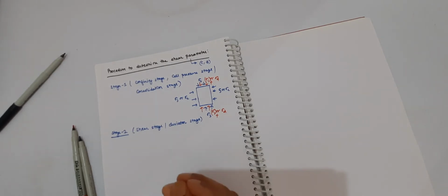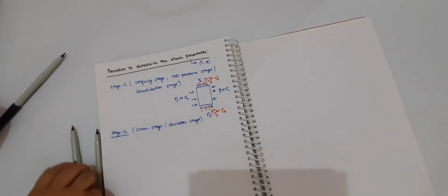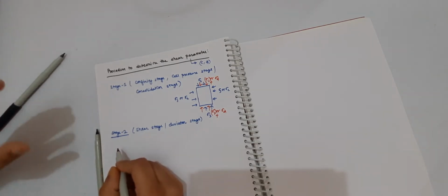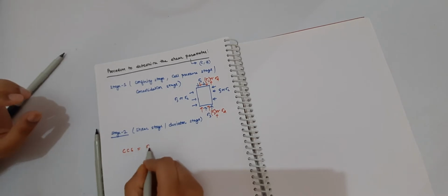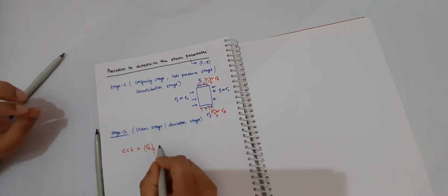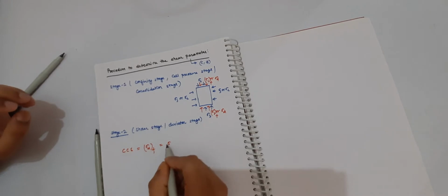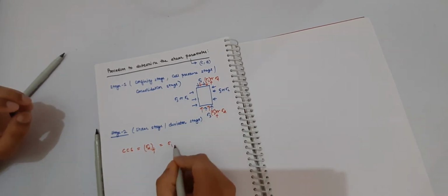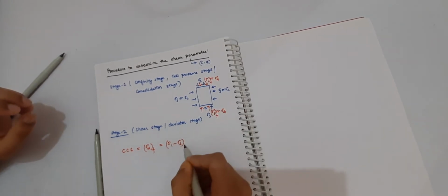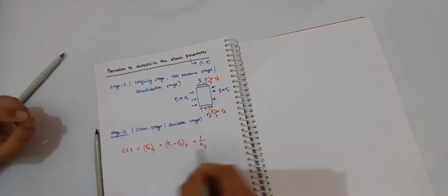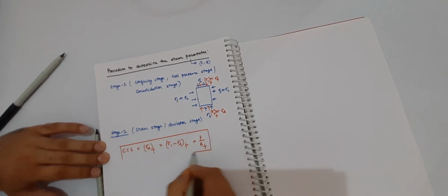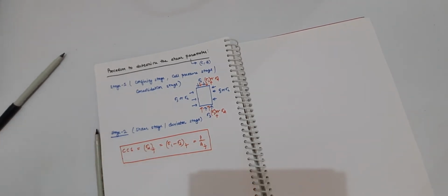As this deviatoric stress determines the failure plane, in triaxial test it will also be known as confined compressive strength. The deviatoric stress is sigma 1 minus sigma 3 at failure, which is equal to load per unit failure area, right?